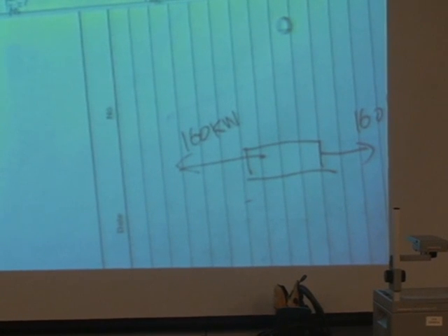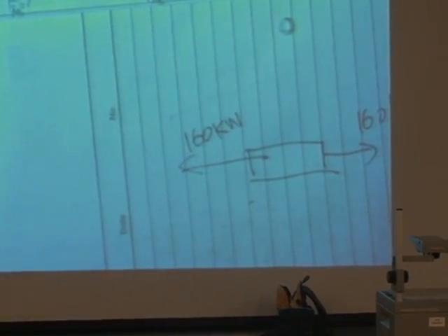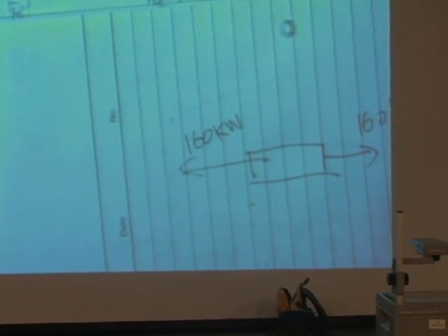So how do we know that the force from the wall to the object is exactly 160 kilonewton in the opposite direction? It's according to the rule of static equilibrium. The resultant force on this object from both directions maintains static equilibrium, so the force at this side cancels out with this side. That's why it does not move at all, and why there is a force of 160 kilonewton in the opposite direction at the same magnitude. This is the way we observe its status and decide what the forces inside are. This will be the fundamental skill for you to solve the questions later.